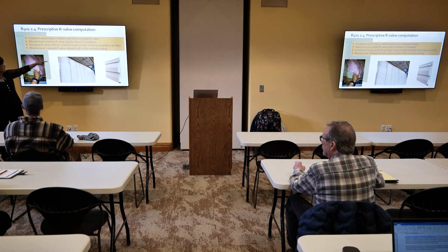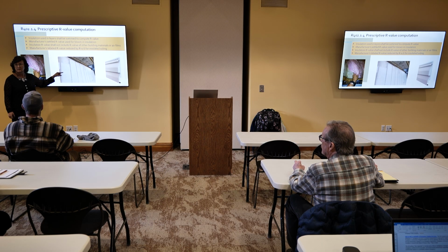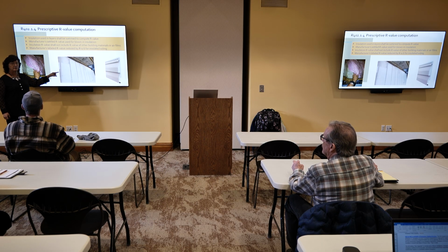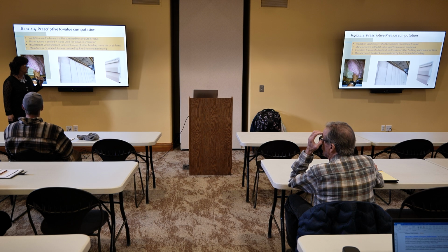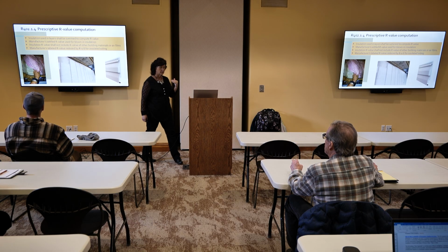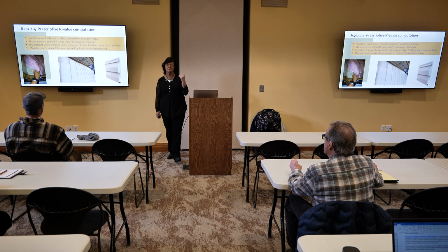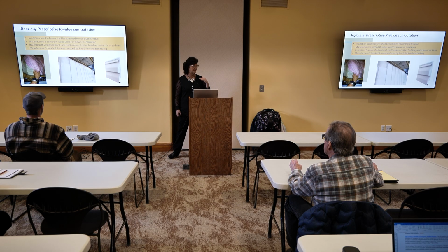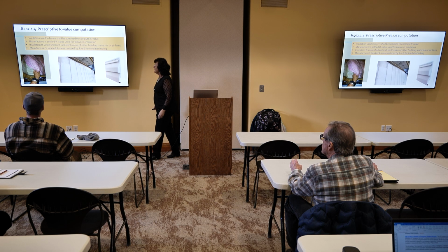The other thing it says, when I install insulation, I have to use the settled R value. We know insulation settles when it's blown in. That settled R value is what has to meet the code, right? Not what it is when you install it, but what it will be when it's settled. It has to meet the R20 or whatever the requirement is, okay?